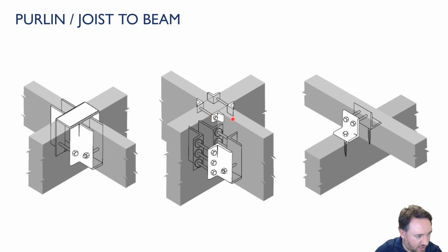But you'll notice that at the top here, it's not bolted, to allow the shrinkage and expansion of this beam due to moisture, right? So I'm only connecting it in one place here, and then if this whole thing wants to move up and down, it can.